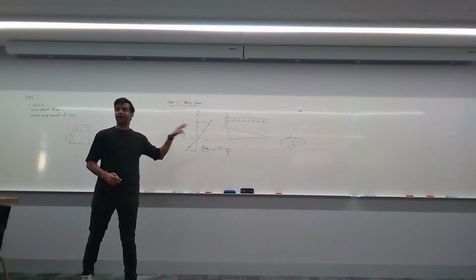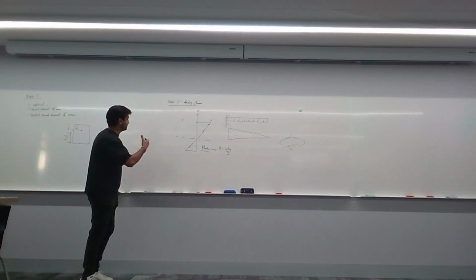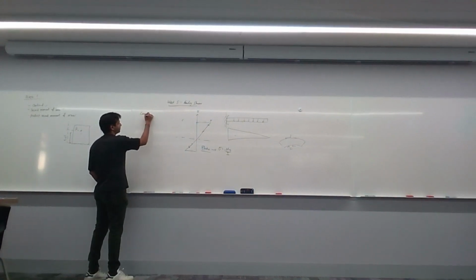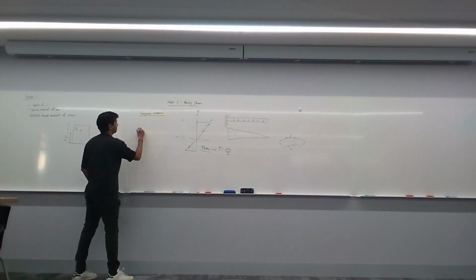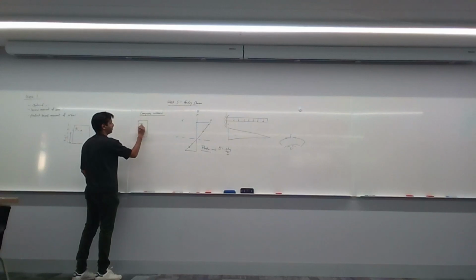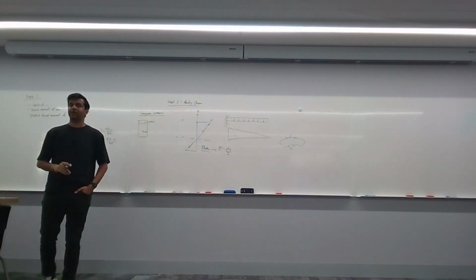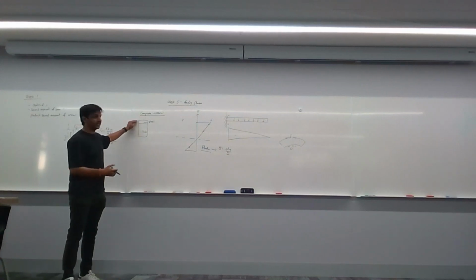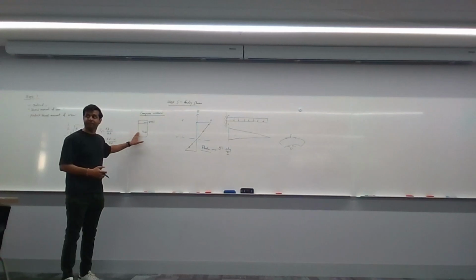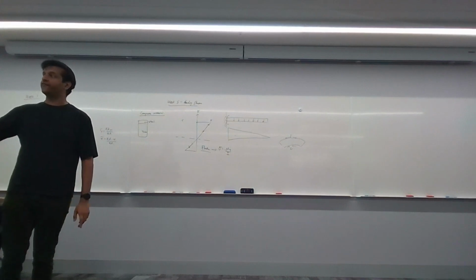Okay? That's the basic part of a single material. Okay? The next thing that the course looked at was a composite material. If you have a composite material, say something like this, where you have timber here, and let's say you've got steel here. Okay? So let's say you have this cross section. You have steel at the top and you have timber on the bottom. And let's say the question asked you, when you're doing these calculations, convert everything to steel.